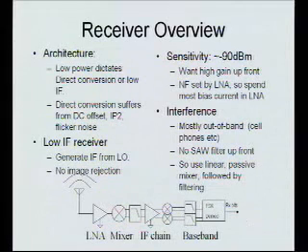When you say no image rejection, do you just mean no explicit image rejection filter, or you also don't do the quadrature thing? Nothing. So it really is an LNA and just a mixer, and nothing else. I felt really not sure this was a good idea, and then I went to ISSCC, and other people were doing it too. I was like, okay, I'm justified. And they were doing it in medical implants, which sounds scary to me, because one day someone turns on a radio in your image, and